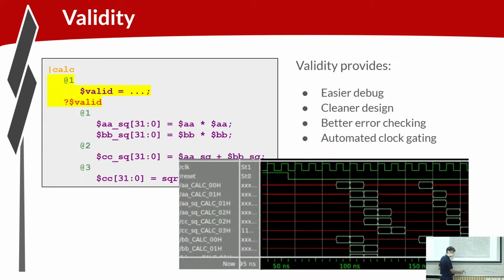And if you really designed your circuit like this, the valid signal would be transitioning for some period and stabilizing on a stable value. What I'm saying is, can you make the valid signal a little offset? Like during the on period of the clock, the valid signal is going high. Like this. Right. So now if I gate the clock and the enable, I'll get one small edge.